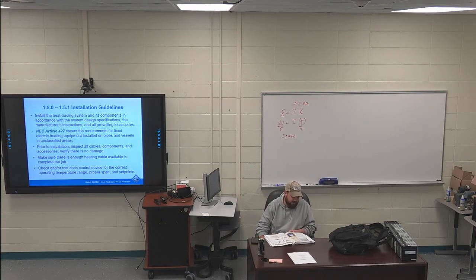Moving on to page 16. I've got the whole note on page 16 in the top left highlighted. If the heating cable is spiraled or wrapped around the pipe instead of being installed in a straight run, additional cable length must be allowed per foot of pipe. The amount of additional cable depends on the pipe size and the distance between the spirals.